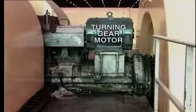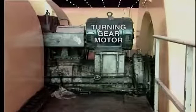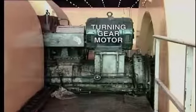Even before we think about admitting steam to the turbine, there are a number of very important maneuvers that must be carried out. If the turbine is returning to service after a long outage, then the first thing we must do is to place the unit on turning gear.